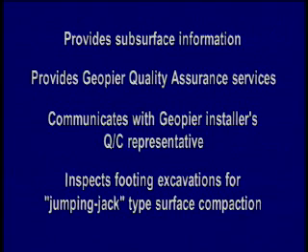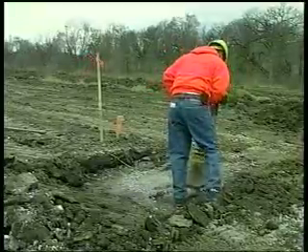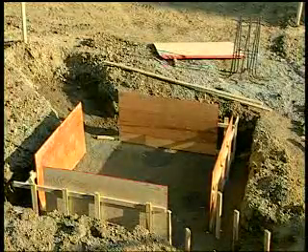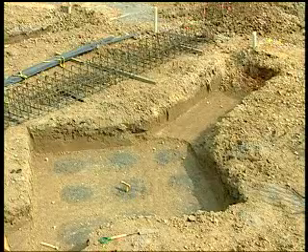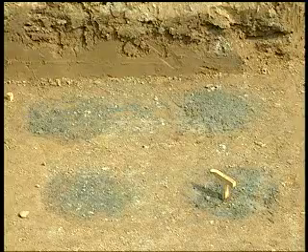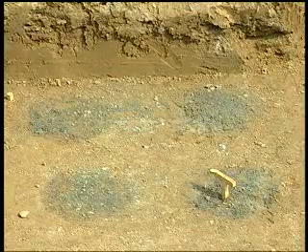Providing later inspections of footing excavations to assure that exposed soils at bottoms of footings and the tops of Geopier elements are compacted properly with a handheld mechanical jumping jack type compactor. A sled type vibratory compactor is not satisfactory. Additionally, assuring that each footing excavation is inspected on the same day as the footing concrete is placed, that water has not ponded in footing excavations, and that the footing bottom conditions in Geopier tops have not been softened by water saturation or by other causes.